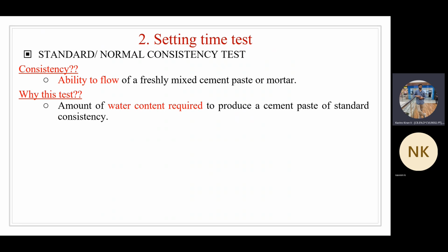But in the setting time test, you will be able to find out the exact quantity of water that is required in order to prepare a cement paste. That exact quantity of water requirement can be determined by using the standard consistency test.